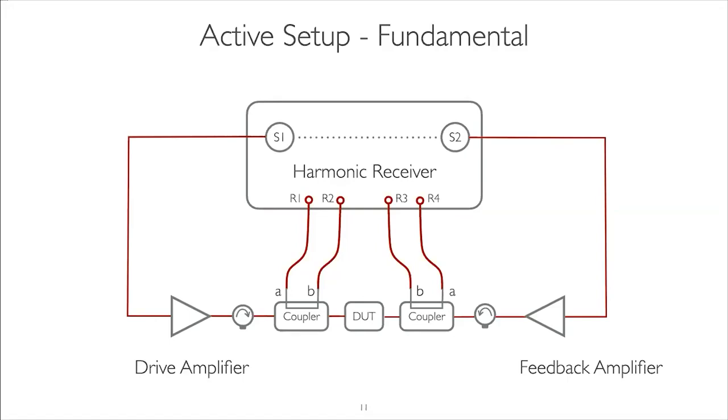Amplifiers are very different in that case. You cannot use a small amplifier to load a very high power amplifier. You need a proportional amplifier on the load to do that. So we'll be looking at that. So again, how do you define the size of that amplifier? The amplifier and the isolators and all that, that's all in a 50 ohm world, okay? So the devices that we test are normally not 50 ohms, in some cases they can be a very low impedance below 5 ohms, 2 ohms, depending on how much power and what kind of device technology you're using.